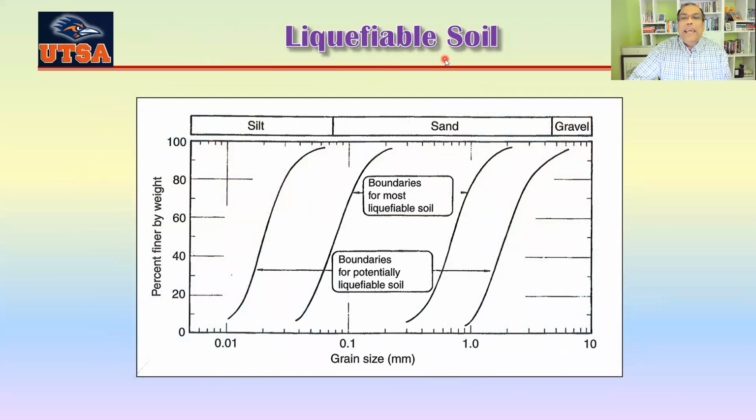Now I just gave that boundary where you can see liquefaction occurs. Liquefaction doesn't occur in clay soil. It usually happens for cohesionless soil. Okay. So when the sand doesn't have any shear strength, it starts behaving like a liquid, right? Sometimes we call that quicksand. Okay, so you can be drowned in quicksand. Anything you put in the sand may sink.